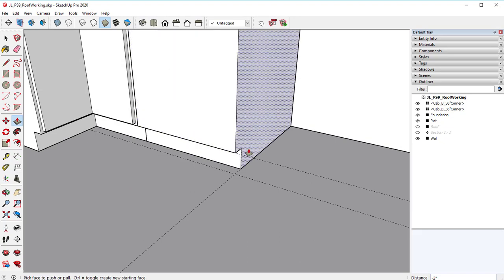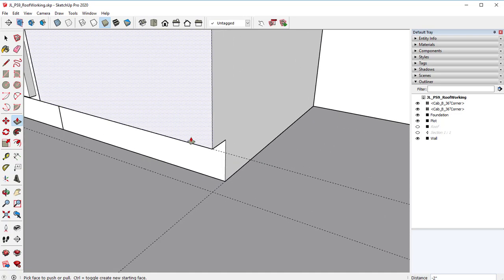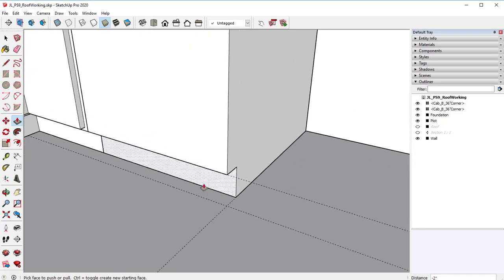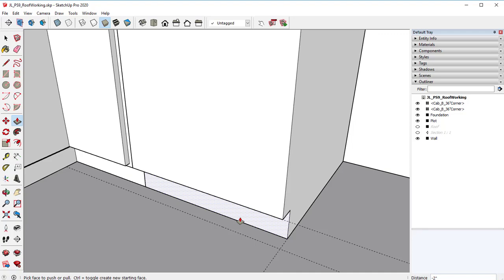If you're ever not able to select a different face, like if I select this and the entire thing selects, then your line isn't all the way across. You have some sort of gap there or something isn't correct. So go in there, zoom in, make sure that everything is correct. Go through the entire line just to make sure that there's no gap. It's directly on the face, all that stuff, and you'll see your culprit at some point.